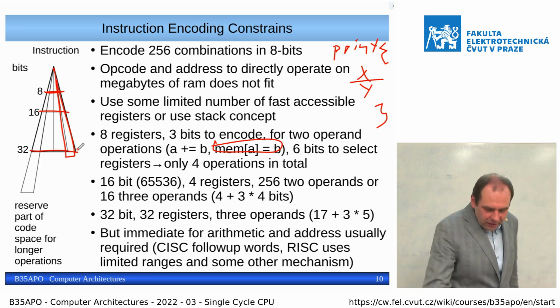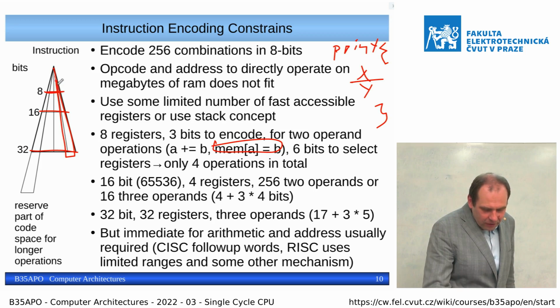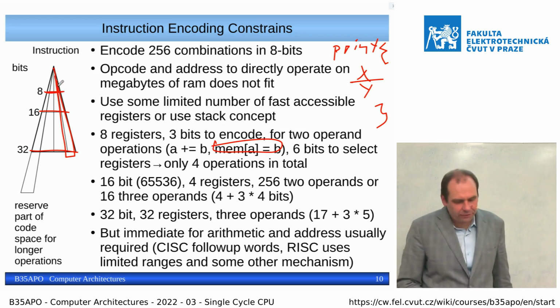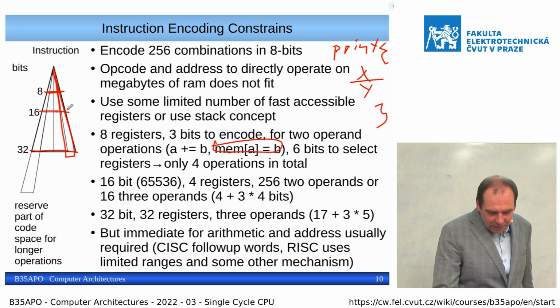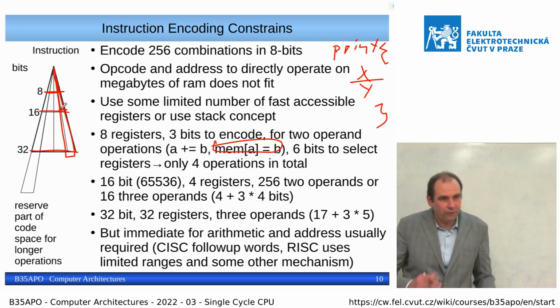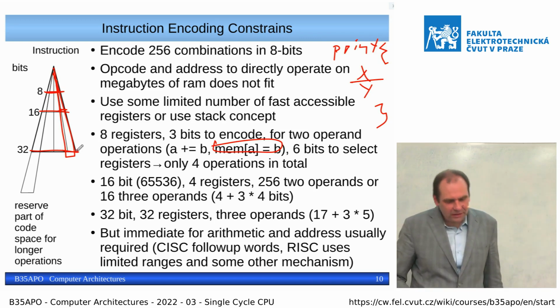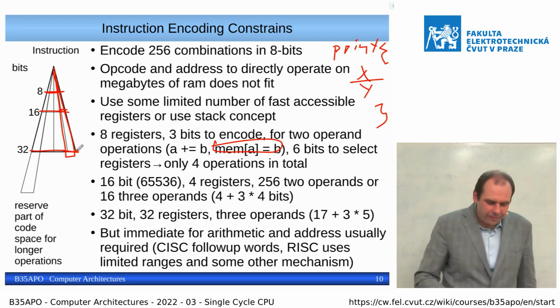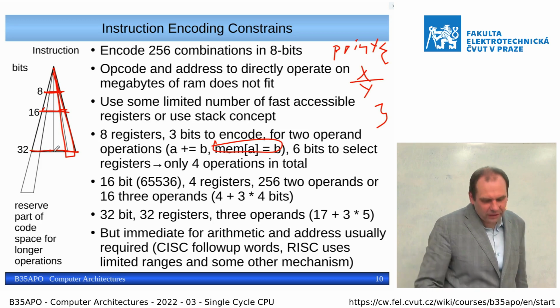Because if you, for example, select 1/4 at 8 bit for some type of instruction, for example for the increment of the register, then at 16-bit, 1/4 is 16,000 combinations. And at 32-bit, it is 1 milliard. So it is questionable which instructions should have shorter codes and block the area for longer instructions and so on.